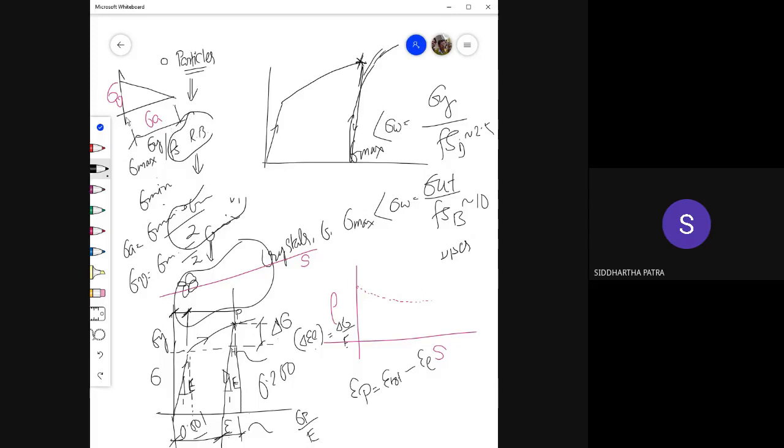And if the average is 0, if there is only a variable load going from minus sigma max to plus sigma max, then you have the endurance strength divided by the factor of safety. I don't recall if that one is Soderberg equation or not, but one of the equations, whether the linear approximation or the quadratic approximation, is Soderberg equation. Now, obviously, if we are working with brittle material, we'll have to change to ultimate stress and a different factor of safety.